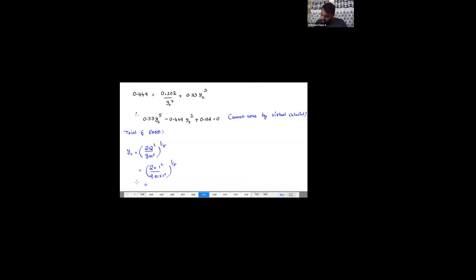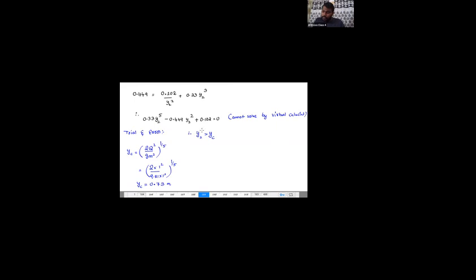So the Yc value is 0.727, about 0.73 meters, which means obviously Y2 must be greater than Yc. Keep that in your mind because after the jump, Y1 and Y2 are conjugate depths. So one is supercritical, the other is subcritical. Already Y1 is 0.5.